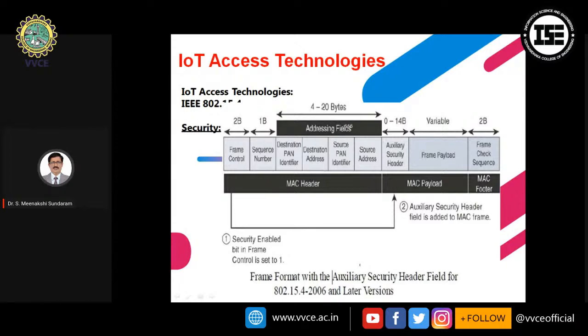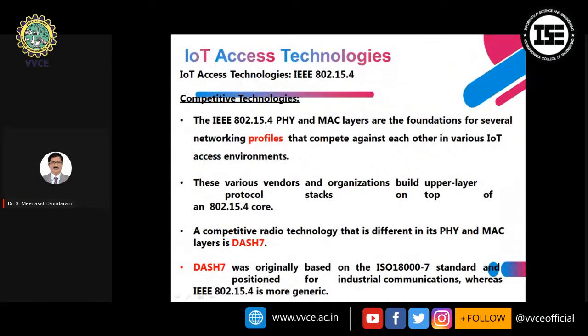So the MAC header, MAC payload, and MAC footer are the major components for the security. The security enabled bit in frame control is set to 1. The auxiliary security header field is added to the MAC frame.